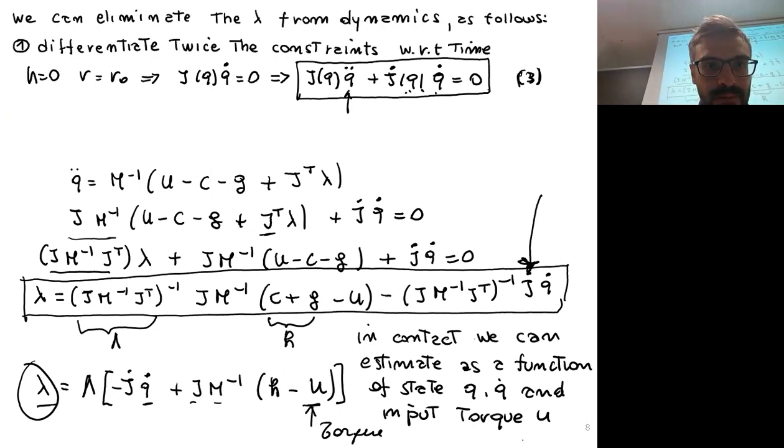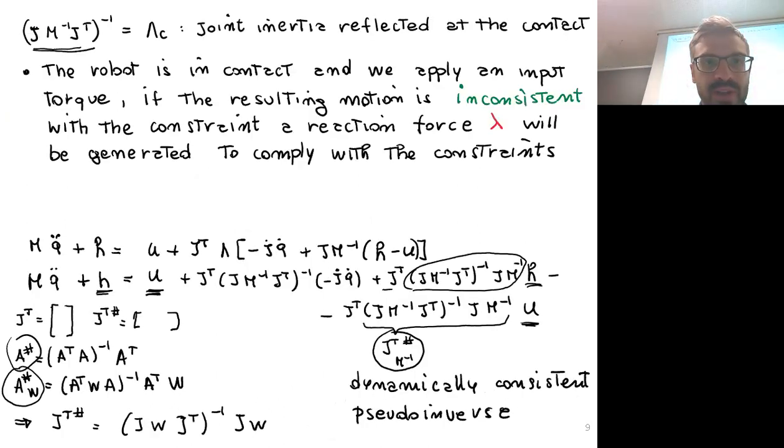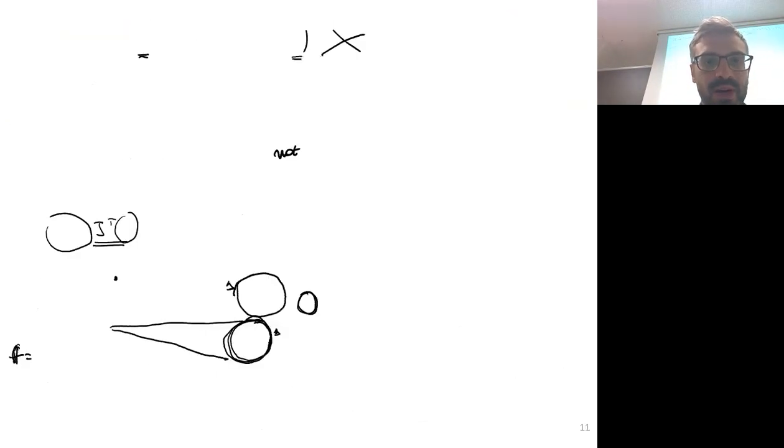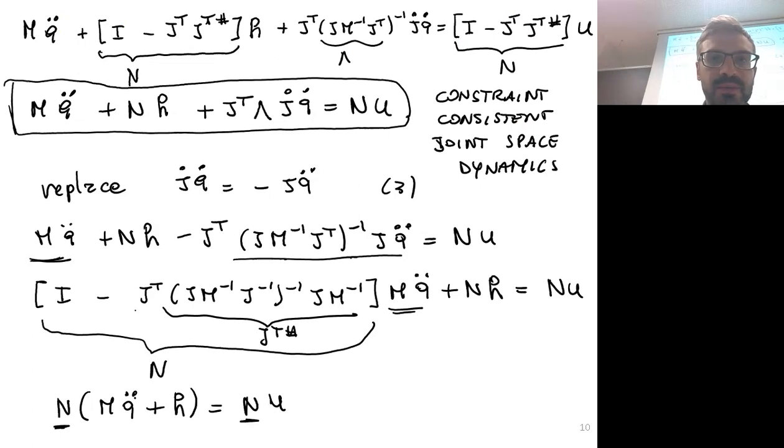And so in case we want to do inverse dynamics, this formula is very nice, because given the motion, we compute the torque that is meant not to violate the constraint, like keeping the end effector in some position. But this assumes that the end effector is already satisfying the constraints at the beginning. So we just apply some torques that are okay.